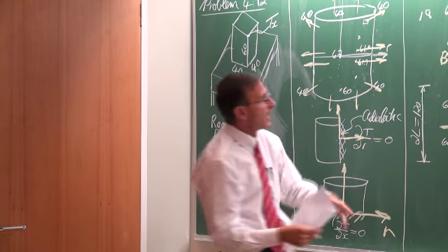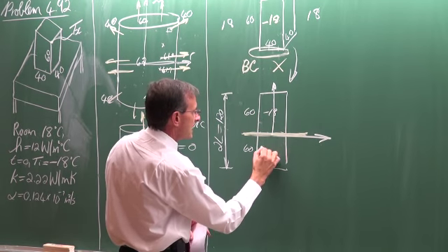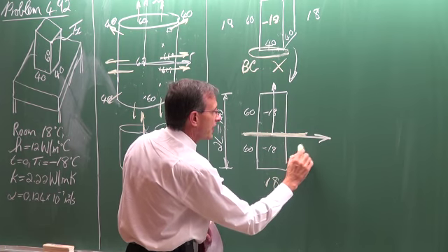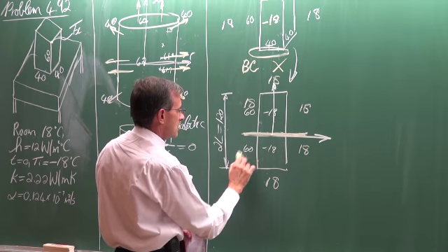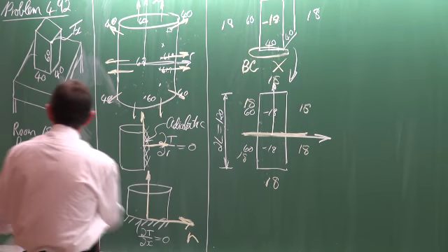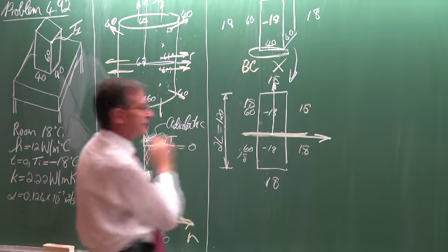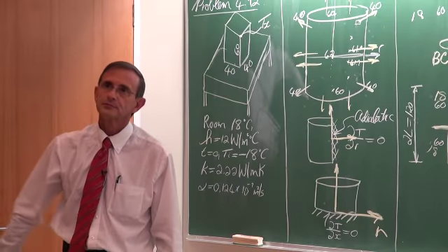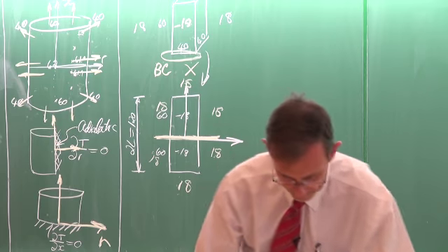So what we have in this case now is obviously the block of ice at minus 18, but now our boundary conditions are correct. It's plus 18 all around, as well as the heat transfer coefficient of 12, everywhere all around the body. You've got it. Right, let's continue and solve the problem.